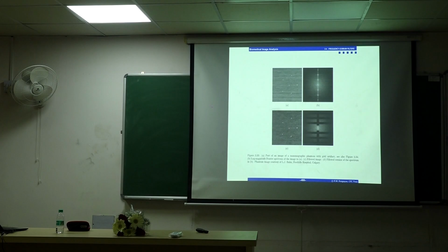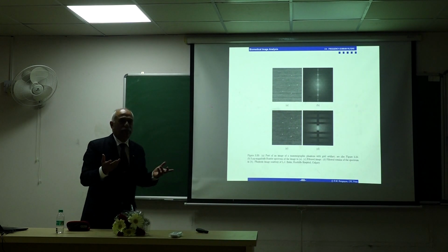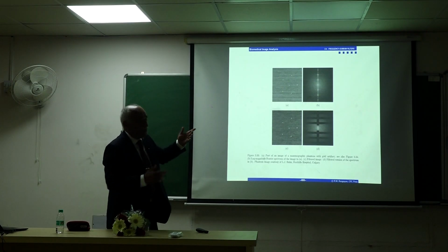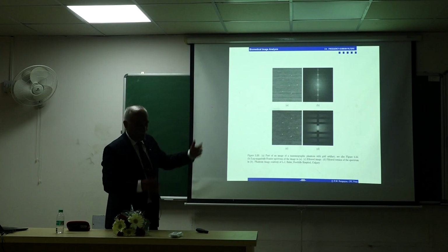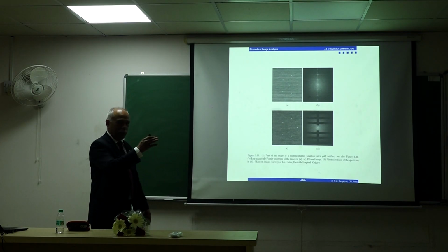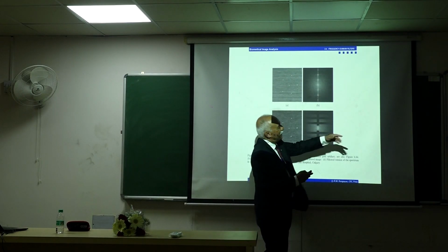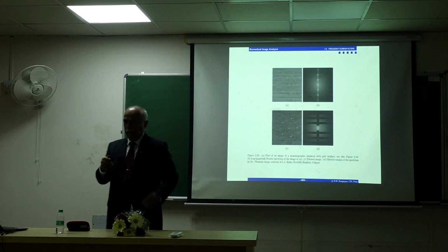What I should have done would be something like this. Keep all of that, and where there is a spike, apply some interpolation, and then keep the rest there. And then where there's a spike, apply interpolation, fill the gap, and make it continuous, make it smooth. Assume that the spectrum is continuous, which may or may not be true, but there should be some continuity. Are those the real values? I don't know. I don't know what was there before the noise. In any case, this is what I got, which is not the best result, but I want to show what works and what doesn't work also. If you want to design a better filter, you could try something like that, to interpolate and fill the gaps.